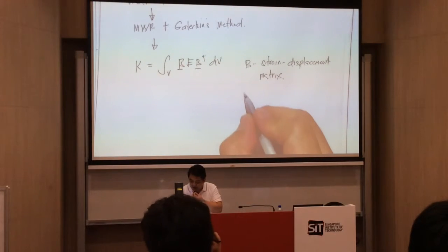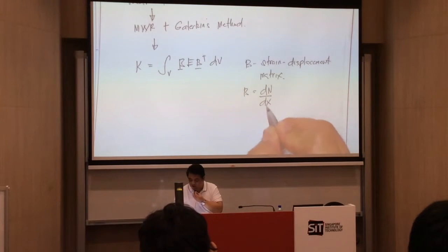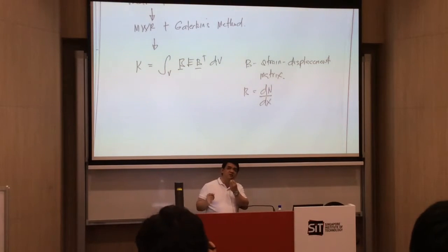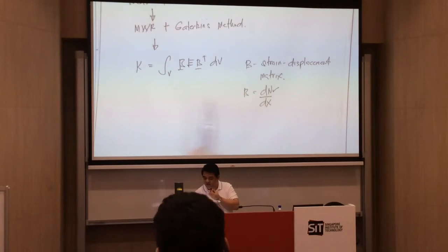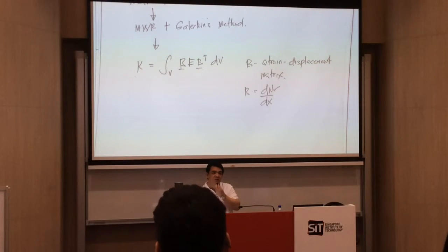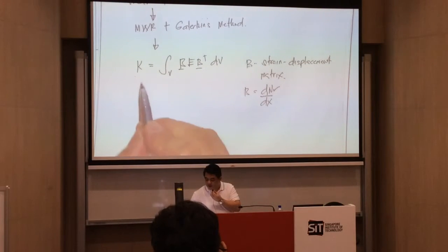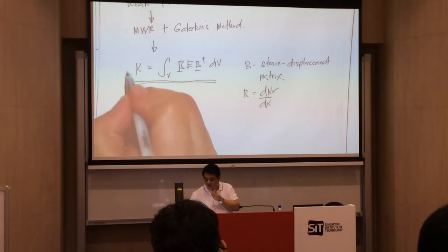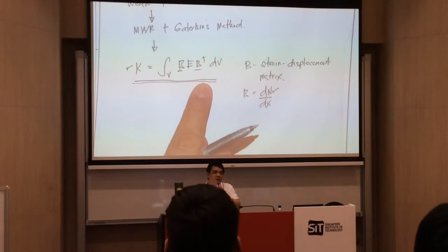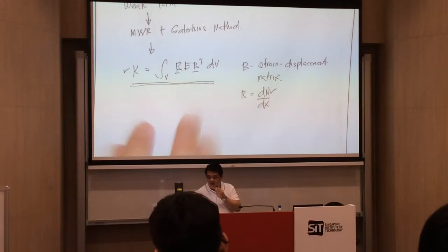And what is this B here? B here can be solved using your shape function, wherein your B is simply the derivative of that shape function with respect to x. So once you have this shape function, you will be able to derive this one here. The symbolic form for a bar, that is k, minus k, minus k and k. So the purpose of using the method of weighted residual is only to get this relationship here, that equation for your stiffness matrix. So you will be ending there.